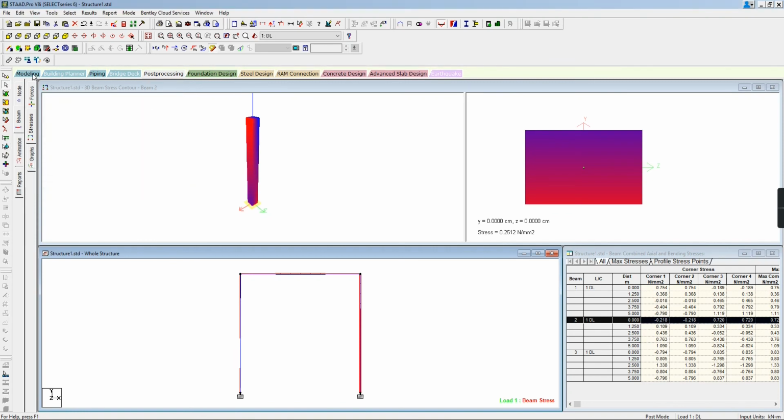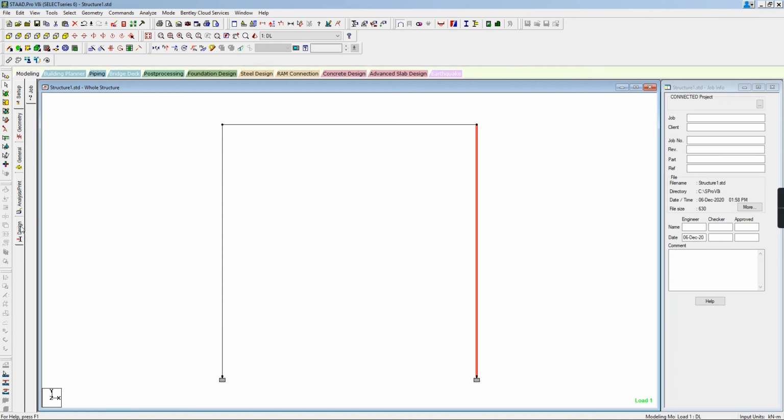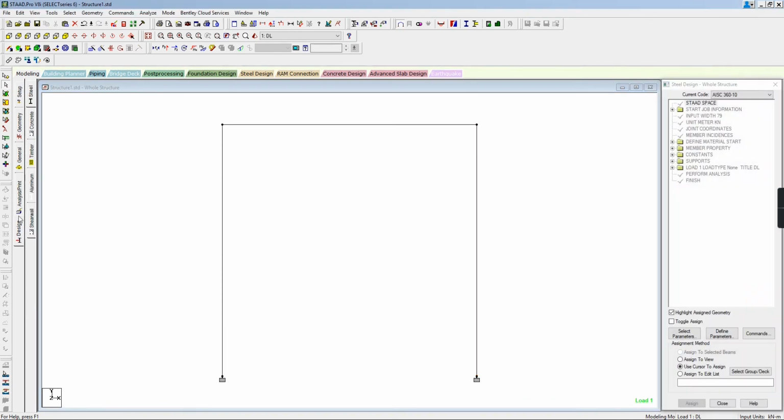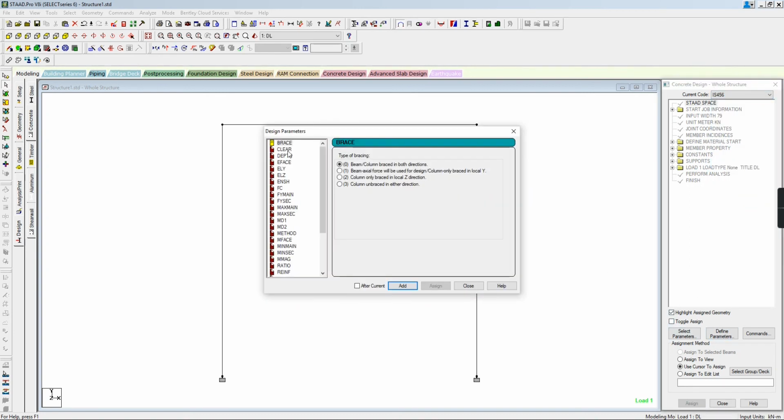Now since this video is on design of column, let me do the design of column. Okay, so I'll go to design, then concrete. I'll be selecting my code as IS456, and I will be defining parameters. So clear cover, let's assume that clear cover is 40 mm. I'll add it. Then FC, grade of concrete as M30, right? So I will be putting 30,000 in kilonewton per meter square. Okay. Add FY as 500, adding it.